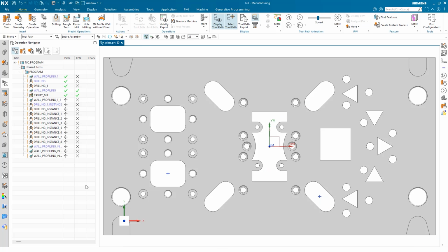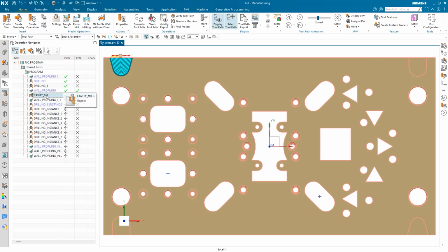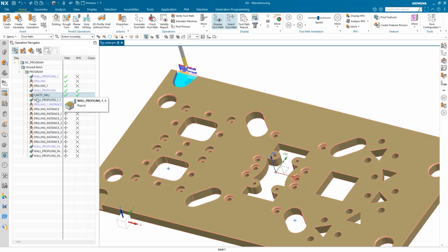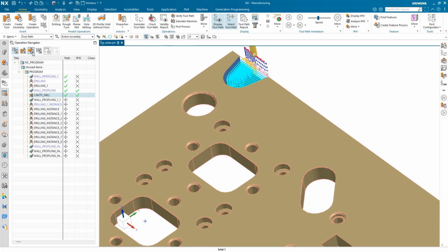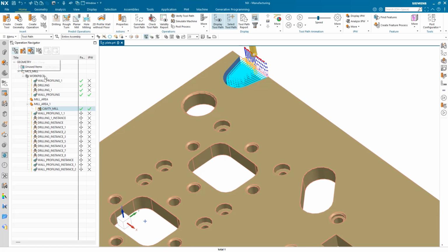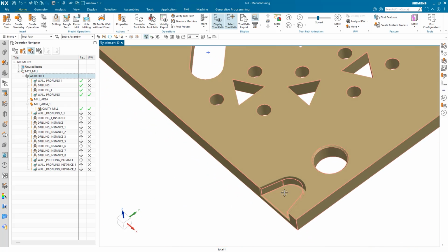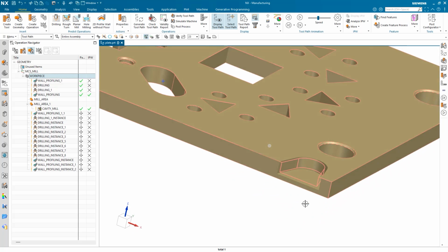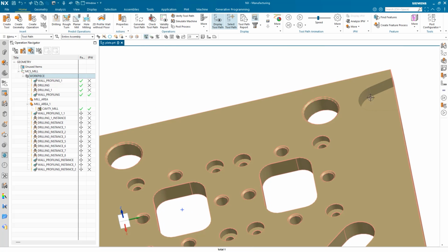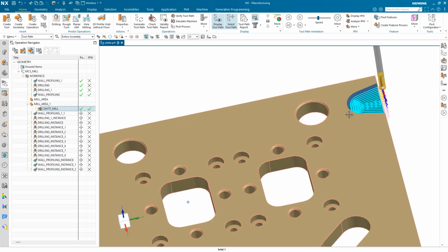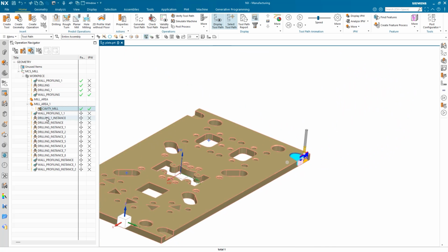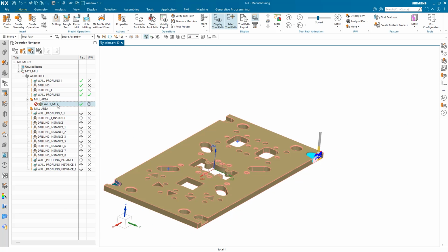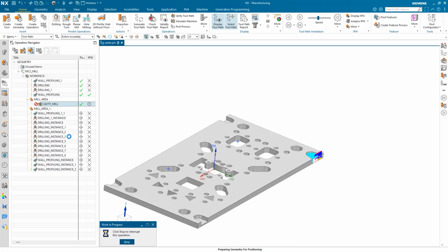When we're using mirrored and transformed operations, we need to be cautious. Let's look at an example why. So here I've created a cavity mill operation. This cavity mill operation's containment is set to use 3D, so it perceives the volume of stock that's present in the part. So this workpiece, you can notice the outlines here. This pocket has significantly less stock than this pocket, which is just bounded. So if I take this cavity mill, which has all of the levels that it needs to maintain its radial and axial depth of cut, and I drag it into this mill area over here,